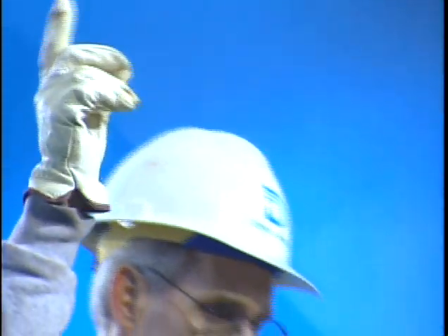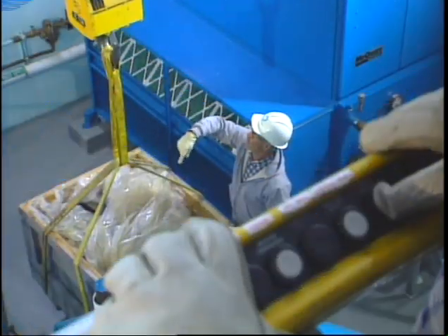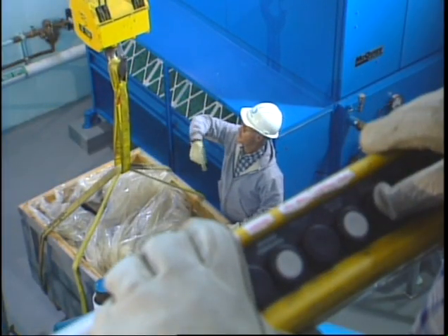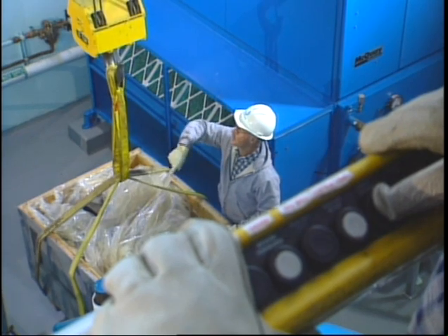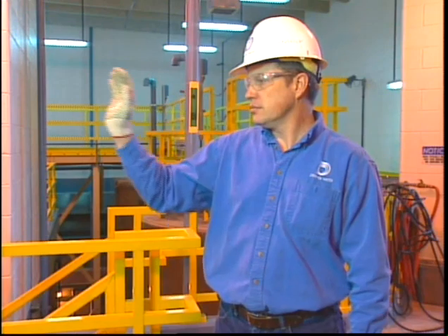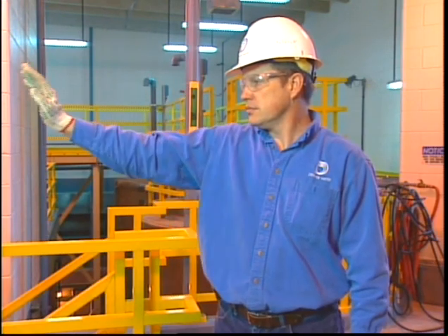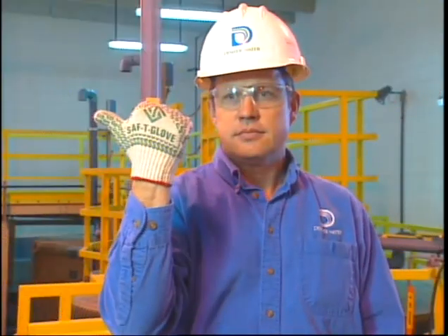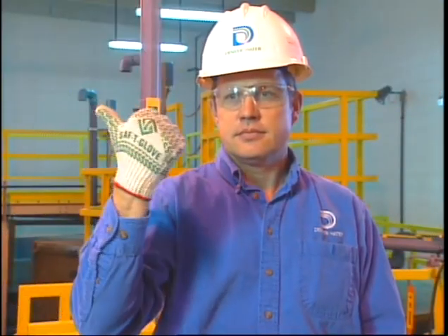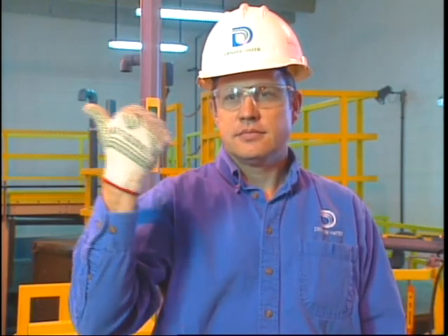Here are the basics. Hoist or up is when the signaler moves an arm vertically with forefinger up in a small horizontal circle. Lower is when the arm and forefinger are pointed downward and moved in a small horizontal circle. Bridge travel is when the arm is extended forward, hand open, making a pushing motion in the direction of travel. Trolley travel is signaled with the palm up, fingers closed, and the thumb pointing in the direction of the motion.